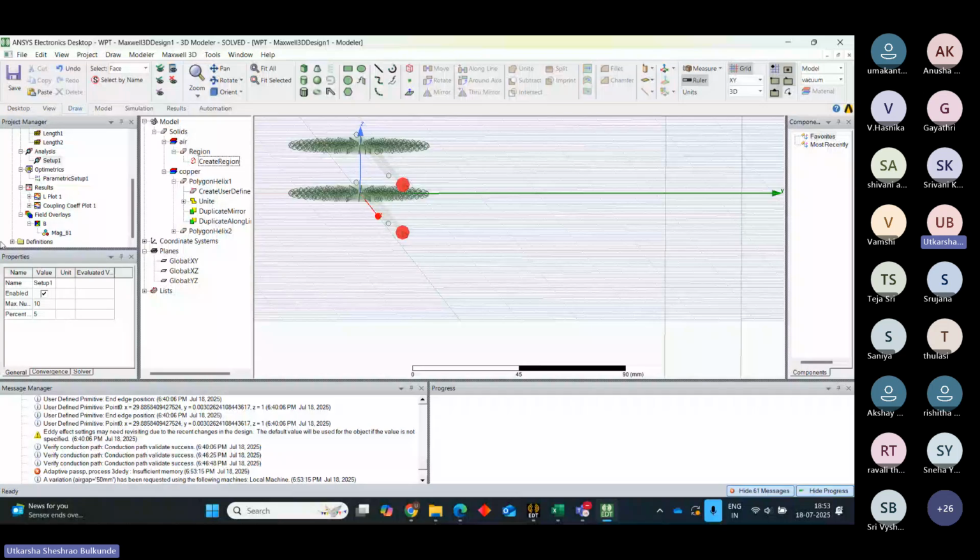It tells you how much flux the primary coil induces, how much of that is getting linked to your secondary, and how much of it is getting wasted, which we call leakage flux. That we get to know through our coupling coefficient, right?